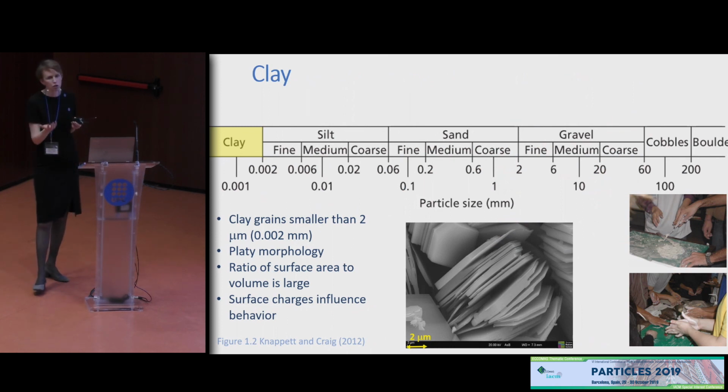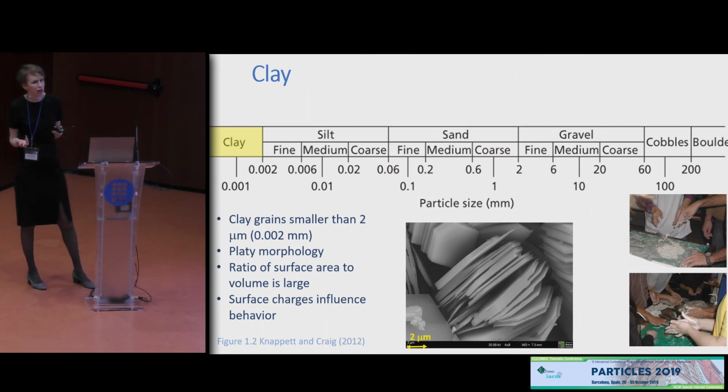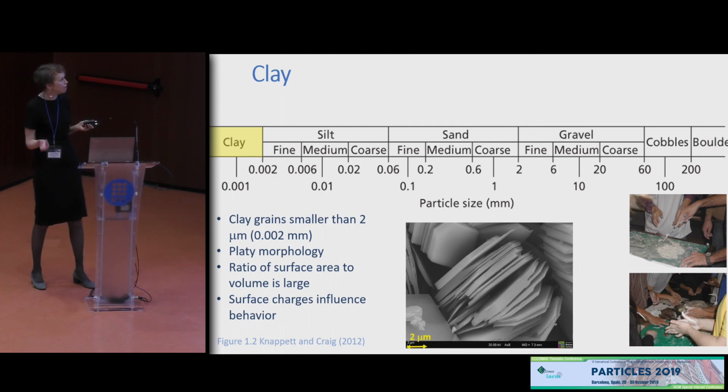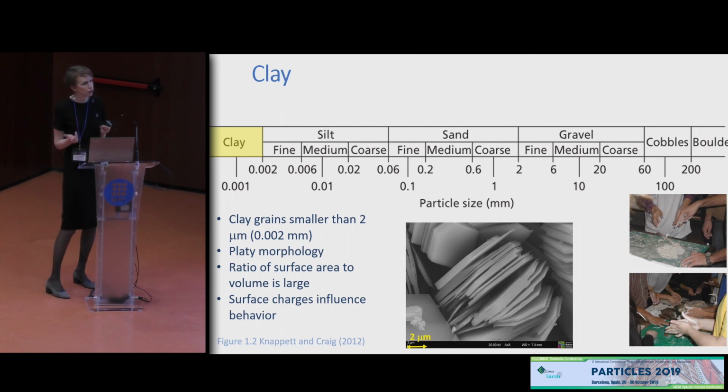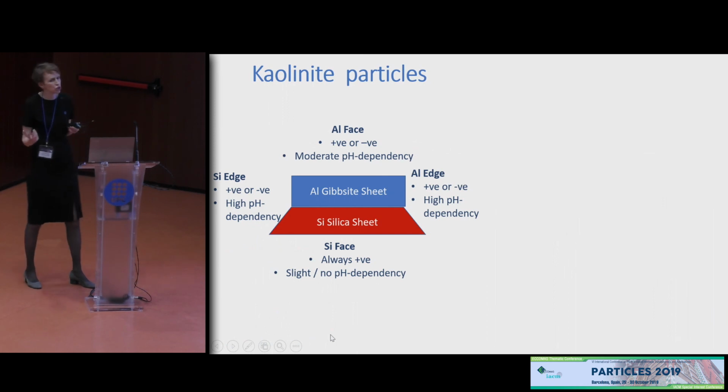The final thing I want to talk about is clay, because arguably clay poses more problems to geotechnics. We'll talk about the dominating influence of the clay phase. With 5% clay in your sample, you're getting a different material. And the challenge is twofold. We have a very complex particle, but we also need to think about the charge and the surface interactions.